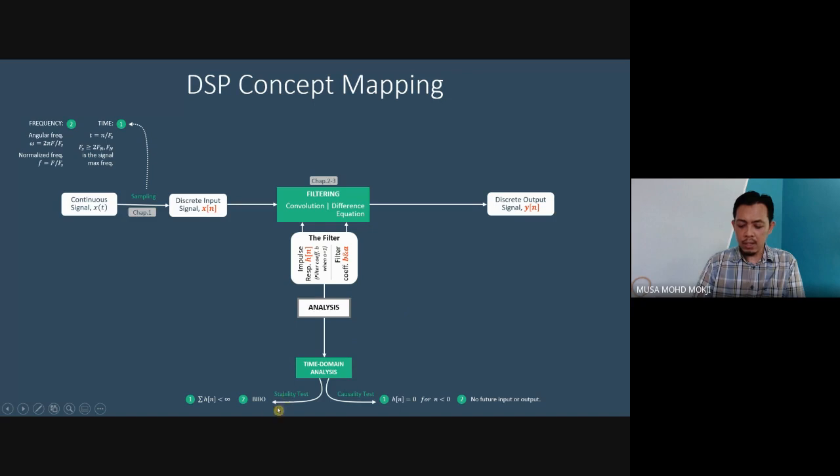One is on the difference equation itself, where we check the input and output. For example, for stability, we check the BIBO effect, whether it is bounded input, bounded output. The second is checking the impulse response. The third is checking the ROC, after we learned about the Z transform, because the ROC is within the Z domain, the Z plane.